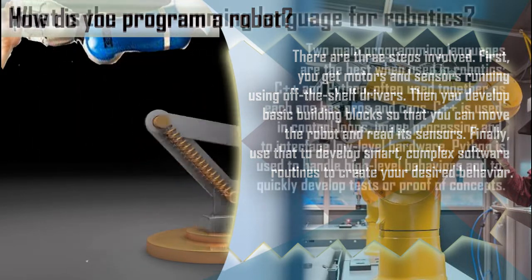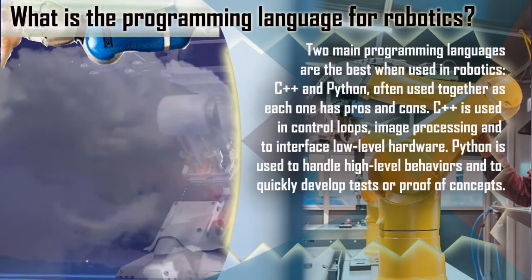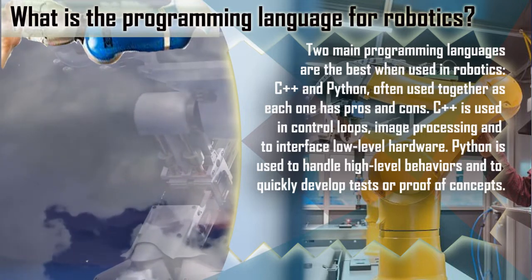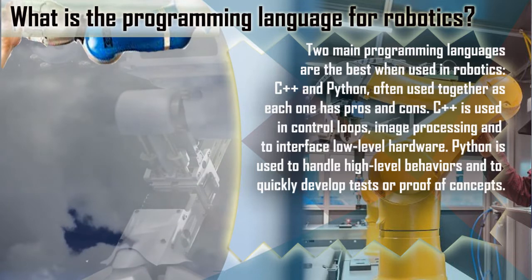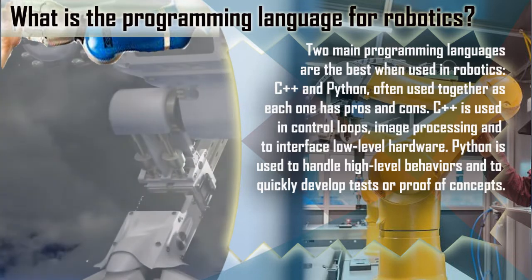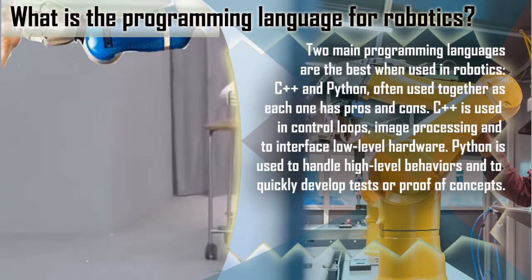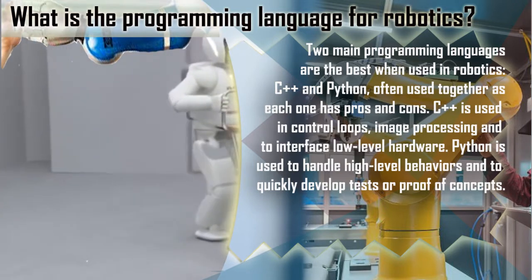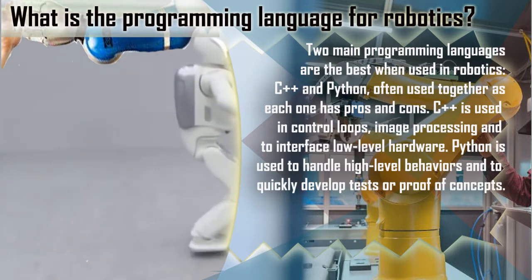What is the programming language for robotics? Two main programming languages are the best when used in robotics, C++ and Python. Often used together as each one has pros and cons. C++ is used in control loops, image processing and to interface low-level hardware. Python is used to handle high-level behaviors and to quickly develop tests or proof of concepts.